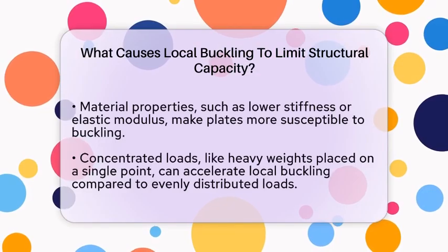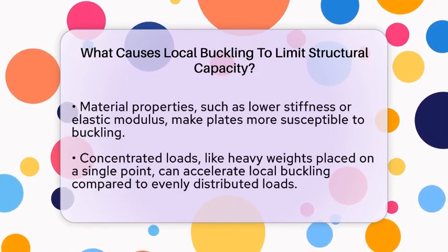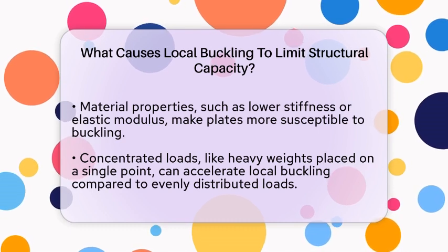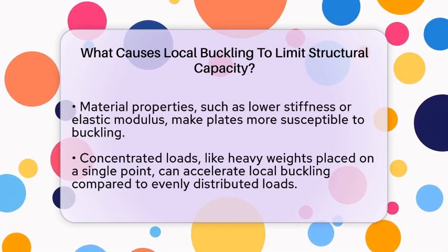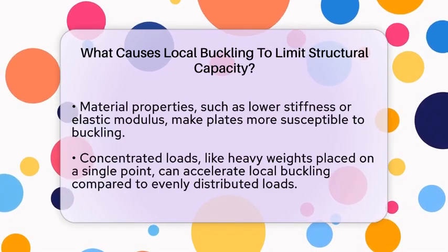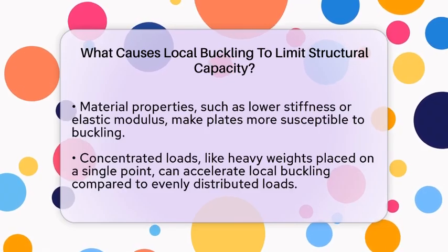Design choices matter too. Engineers often make sections with very thin walls to save weight or increase efficiency. But these thin-walled sections are more vulnerable to local buckling. They can buckle independently of the entire structure, limiting how much load they can carry.